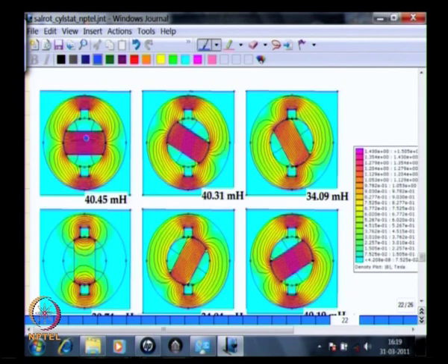Now here, if you see, the flux density levels in the rotor are quite high. The flux density levels in this place and this place are quite high. If you look at what that level might be, this table says that the flux density in that area is likely to be greater than 1.5 Tesla in the middle, and then goes down to about 1.27 Tesla or so, and then that is distributed here. In this position of the rotor also, you find that there is considerable flux density here. In these simulations, the stator winding is excited, there is no excitation on the rotor.